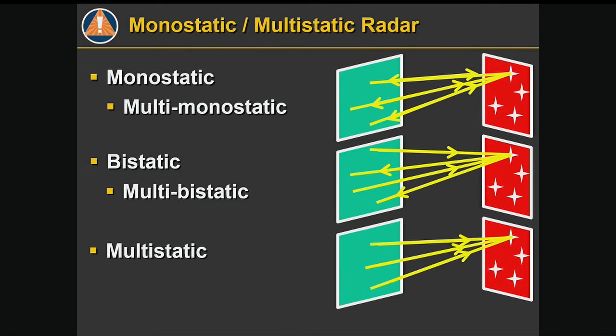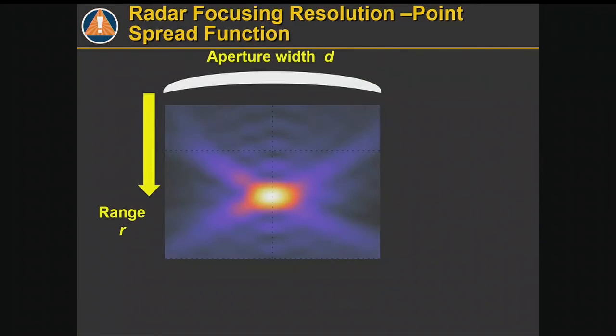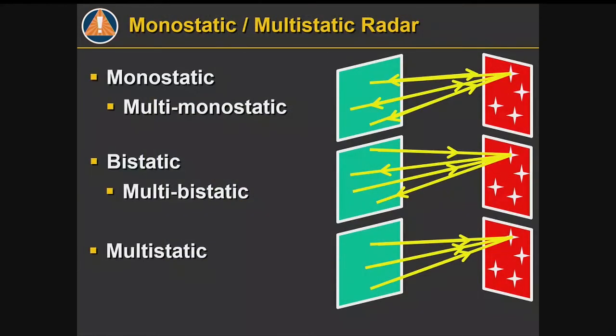But the best of all these would be a multistatic system, where you might have multiple transmitters and multiple receivers. In fact, I drew it with multiple transmitters here without showing the receiver lines, but the most effective means is when you have multiple receivers and you can digitally combine these for various points in the target region by adjusting the phases of each receiver signal.